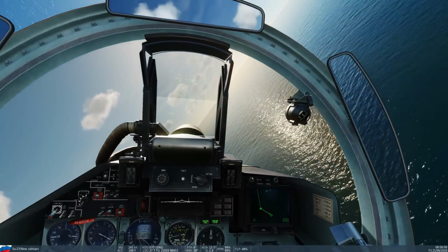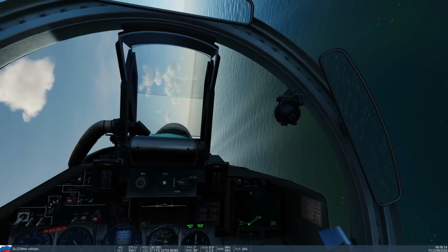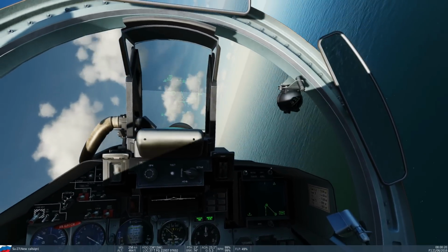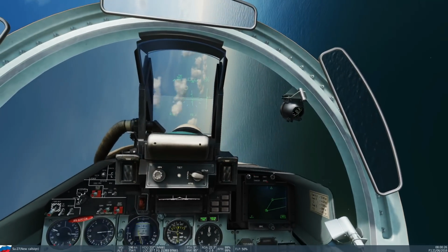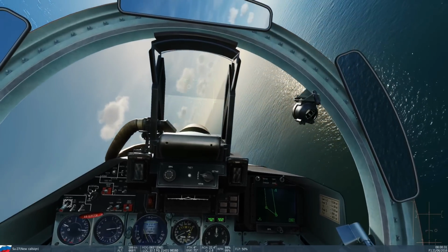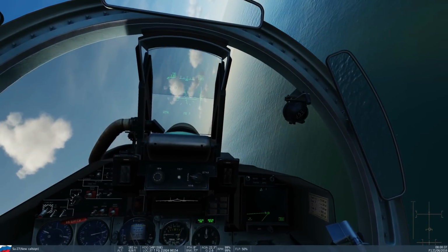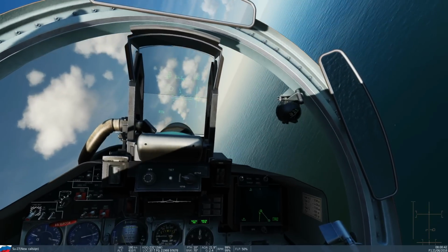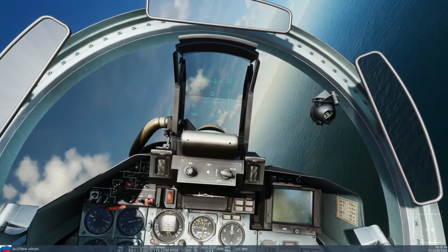Again, it's a pretty good, robust augmentation on the pitch here. So I'm just going to full back stick it. Interestingly, I can't get my controls up for some reason, but never mind. Oh, of course I pressed the wrong button. Right, 190 knots, 22 degrees angle of attack. It's a big thunker. The problem with this is its thrust to weight ratio is not that good compared with the others, and it's a massive drag machine. It's created so much drag, especially in the angle of attack. I guess hence parts of the Cobra maneuver. So you can see we've got it stuck there at 180 knots at 22 degrees alpha.